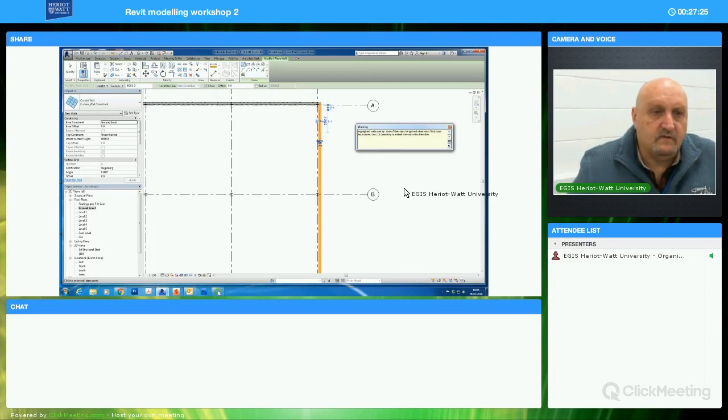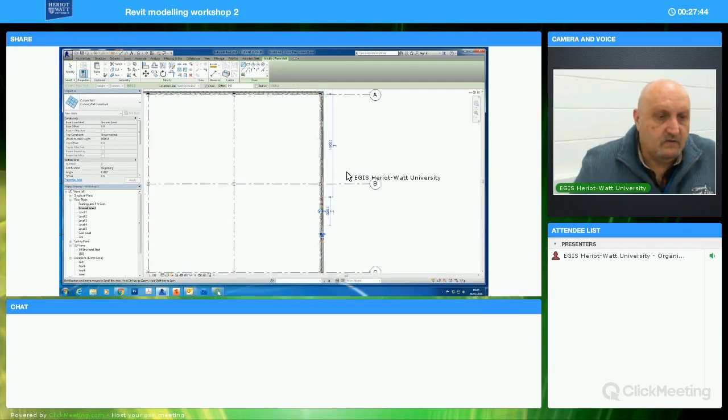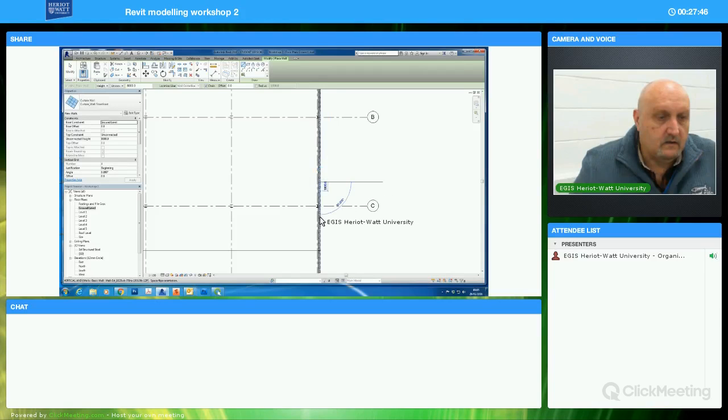warning telling you that you've highlighted walls overlap. Clearly they overlap, you just put one inside the other one, so it's a kind of stupid message. Just ignore it, and I'm going to make them vary in size a wee bit. Just make sure you have it in the middle of the wall, make sure you get the dotted line. Some bigger ones here.